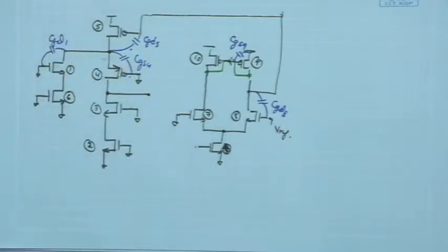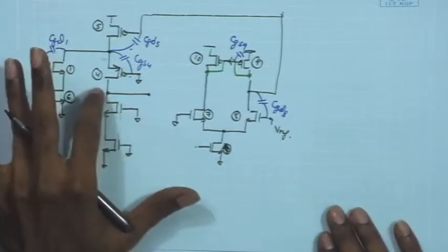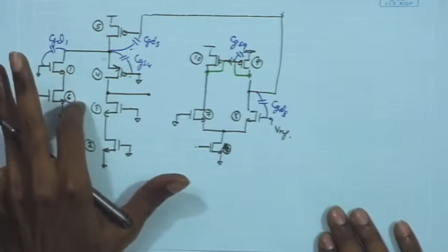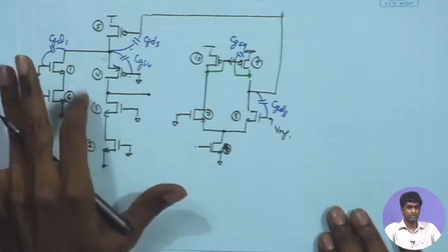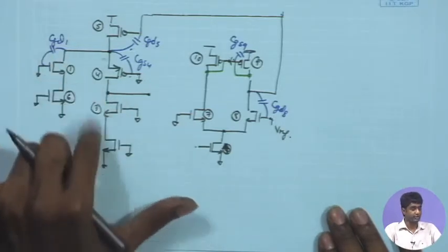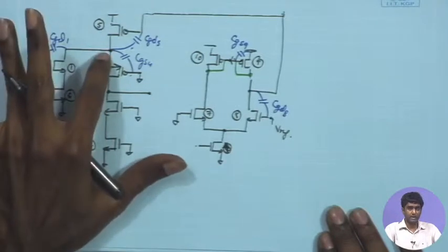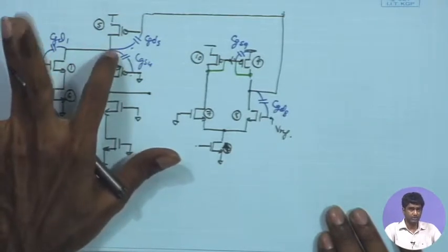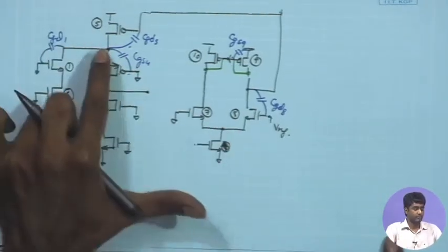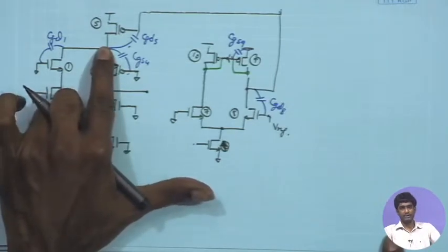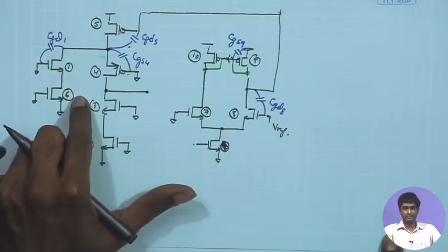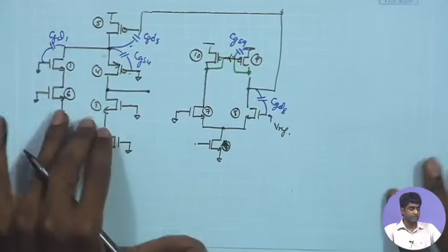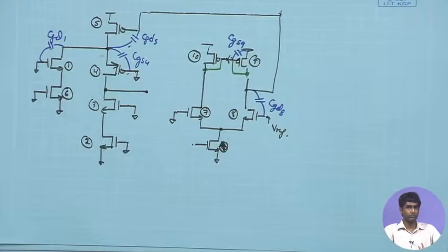Towards that end, the target is that the overall capacitance over here, the compensation capacitance or the load capacitance that we are adding, or which is coming by itself because of the next loading stage, is at least around gmro times the net parasitic capacitance over here. Therefore, if the capacitance over here becomes too large because of other design constraints, the compensation capacitors to be added can become large, so we are trying to identify the different components of the capacitances that are going to come in.